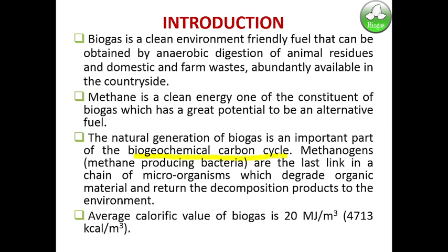In this digester tank, above there is an outlet for the biogas produced, and in the lower part is the outlet for the effluent or slurry storage, either a drying process on a slurry bed or a slurry pond, whatever you may call it. So there are two parts here: first is gas collection, second is slurry collection. Then microbiology is involved, because the methanogenic bacteria are the main part of converting the biomass to biogas.